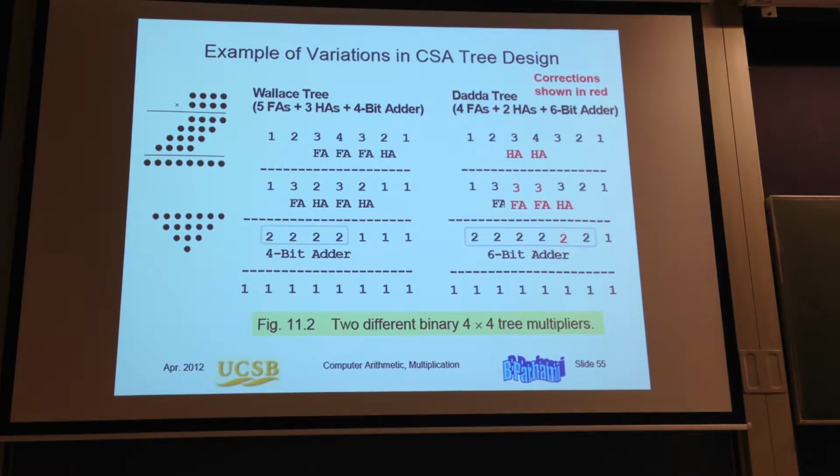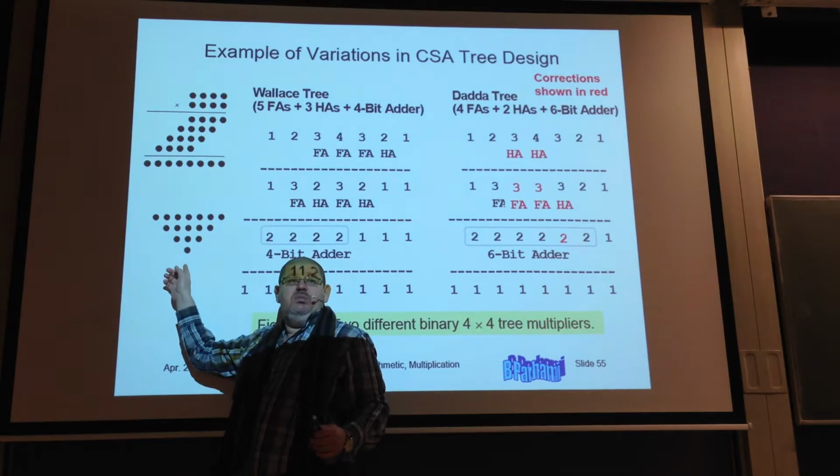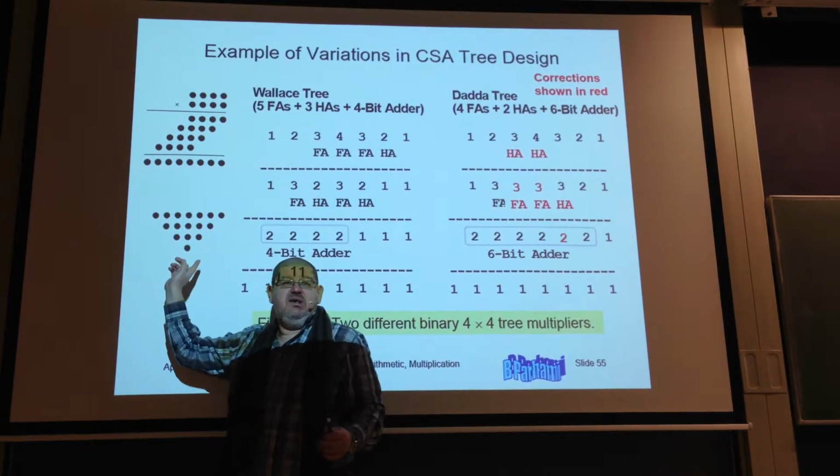When I think about the production of these dots in a serial fashion, the fact that I put it here is because I'm doing the multiplication of this with this, and it is kind of logical to write it in this way. But these products are AND gates which are working in parallel, and the fact that I'm rewriting it in this way is not relevant. What is relevant for the delay is the height of the tallest column, because that will determine my delay.